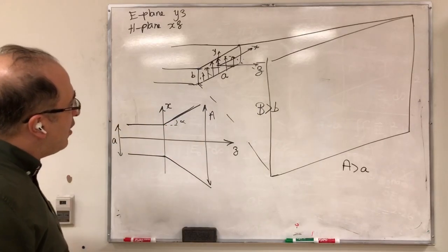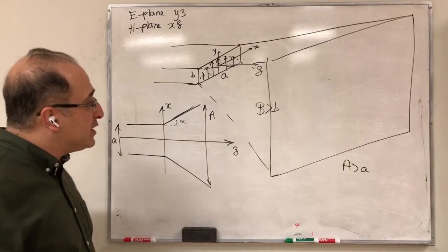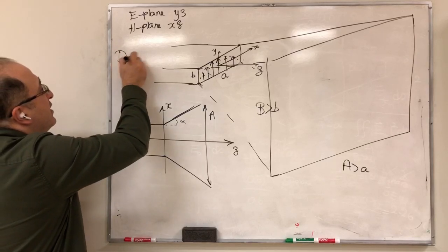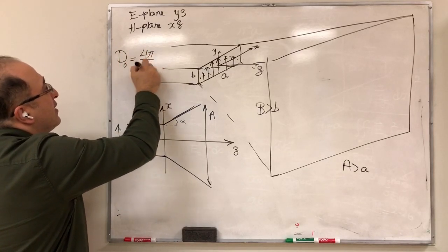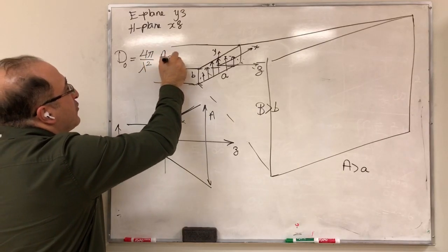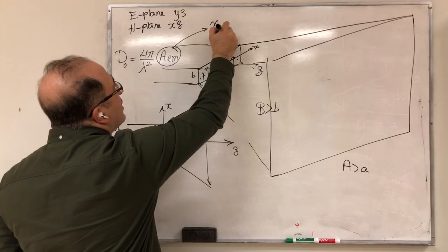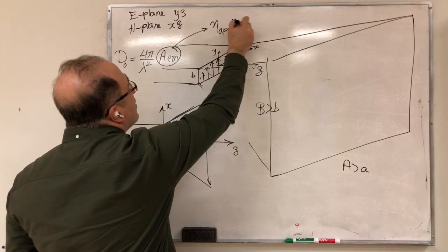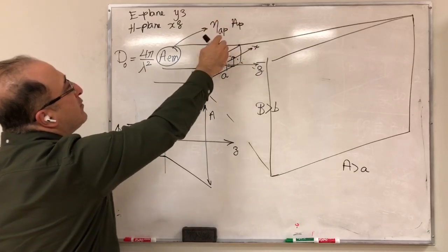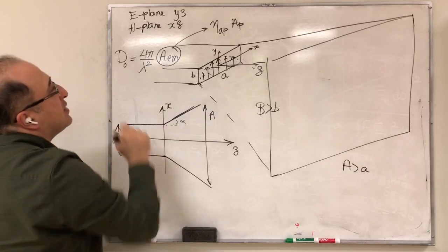So now, how should you flare out? I mean, what's the effect of this? Because you might say, okay, we've learned that directivity is 4 pi lambda square, and then I have A_em from before, but this A_em is related to aperture efficiency times physical area. For example, for open-ended waveguide, this was 81%. This was a small a times a small b.